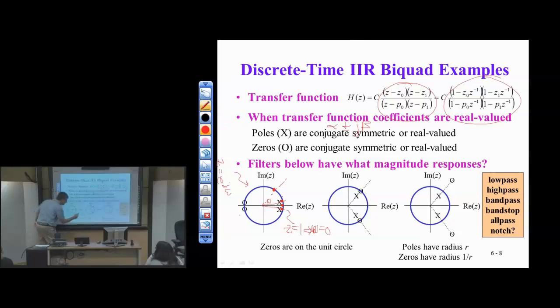And if you look at this, I have a small distance from z equals 1 to the pole location and a small distance from z equals 1 to the other pole location. And those are both very small distances. They're in the denominator, so I'm going to get a very large magnitude even at DC, if these poles are really close to z equals 1.